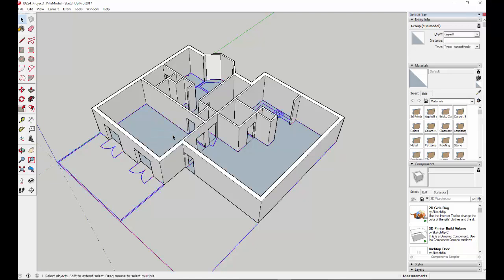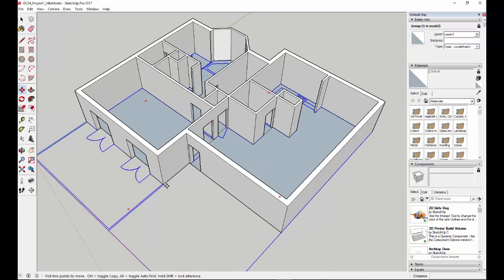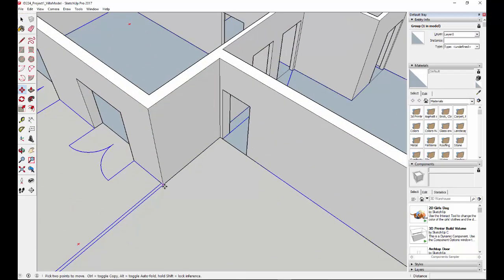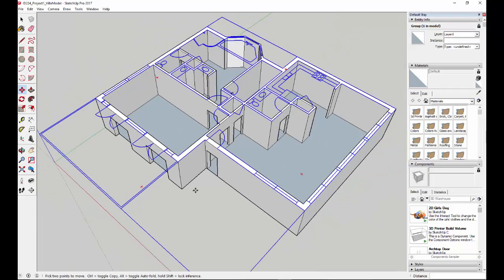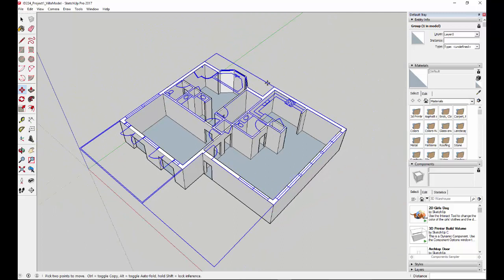So it goes from red to blue. It's still highlighted, and what I want to do is move it from where it's located on the bottom all the way to the top. So the easiest way to do that is with the move command. With the 2D AutoCAD floor plan highlighted, I click on move, and I'm going to zoom in just a little bit. I want to snap to the floor, like where the floor and the wall meets, right here in this corner. And I'm going to move it up to this corner and make sure your purple circle is directly on the corner. Hit click, and you will see that we moved the two-dimensional floor plan to the top part of our model.